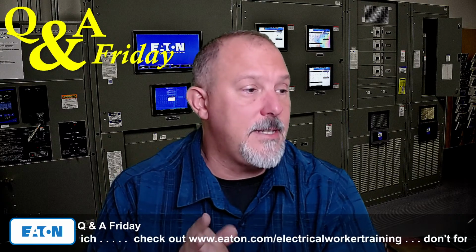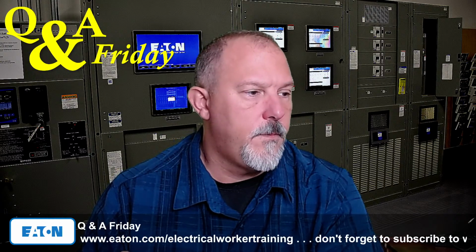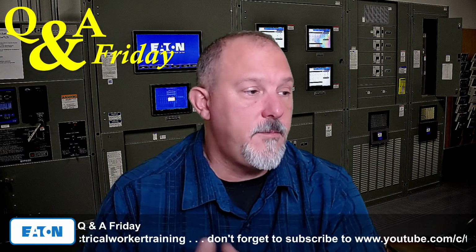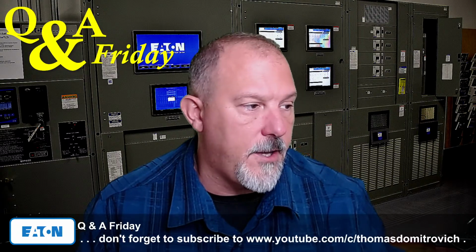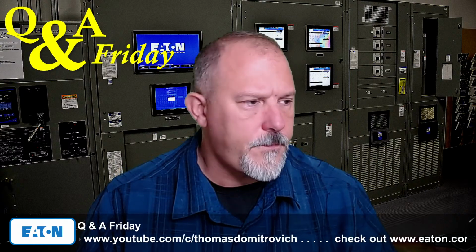To me, %Z, when the transformer is shorted, changes at the higher kVA value. It would seem it would have to be a manufacturer standard to mark the %Z at the lower kVA value and not something of electrical theory that %Z stays the same. Okay.